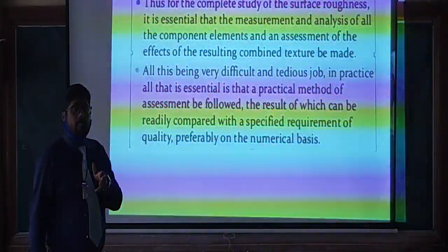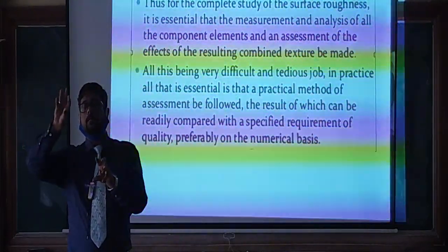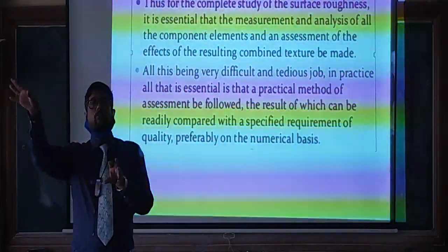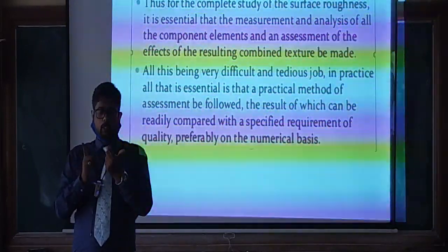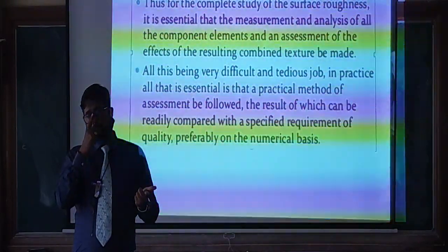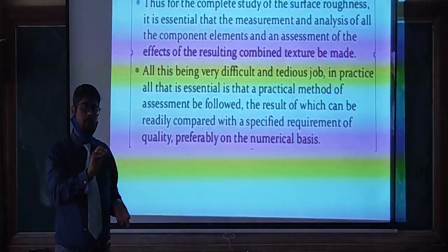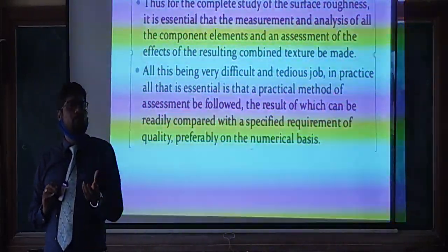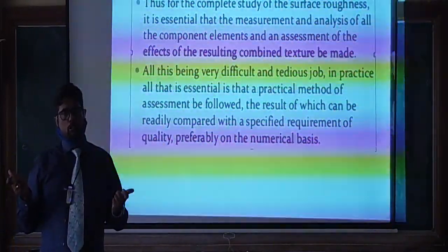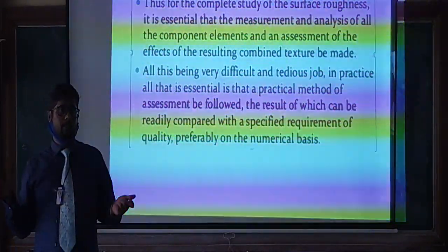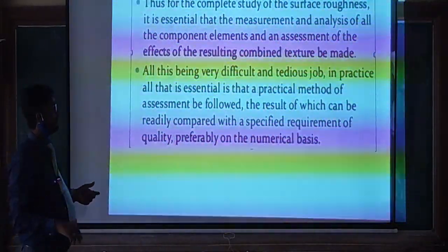Assessment of that is the effect of the parameters of the cutting tool. The cutting tool is one parameter. There are different cutting tools, like carbide tool, polycrystalline diamond tool, and next, CBN, cubic boron nitride tooling. Which type of tool are you going to use for a specific material? Let's say if I am using EN8, then carbide is recommended, polycrystalline diamond is also recommended, and CBN is also recommended. But the cost of that tooling is very, very high, so instead we are using carbide tool.